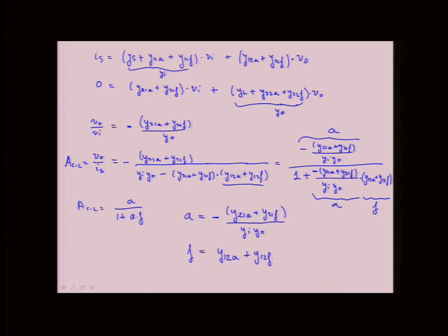Usually, these Y parameters for the amplifier, I can find them very easily. I just map the amplifier; for example, if the amplifier was a transistor, GM would be Y21A, right? And then I just need to find out what those parameters are for the feedback network to be able to plug in here, and from here essentially get my A expression for F, closed loop gain, even the impedance formulas, right? And then I'm done.